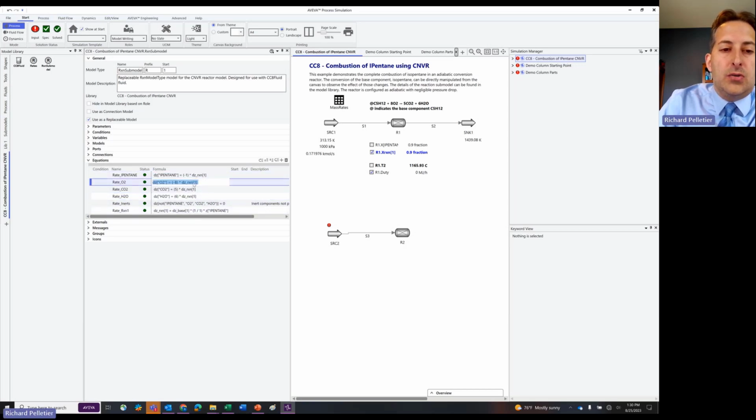So the way that we write our equations typically, we relate the individual components to the overall reaction equation, and we input the stoichiometry there, right? So every time this reaction occurs, it's -1 isopentane, -8 oxygen, +5 CO2, +6 water, right? That's how much we're utilizing based off of the main base reaction here, right?